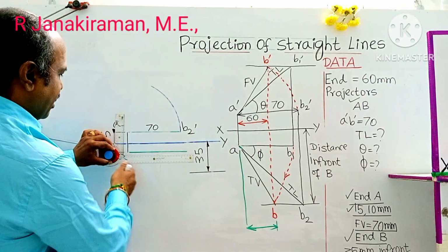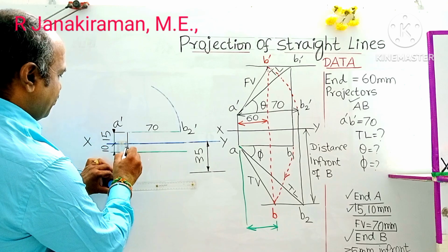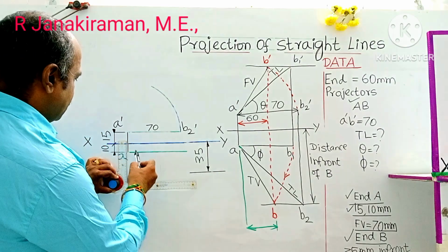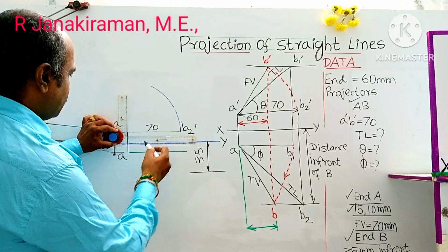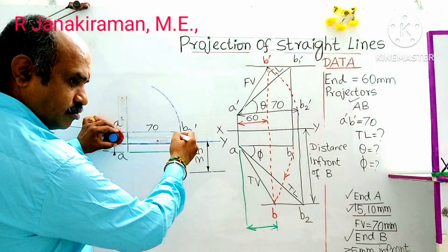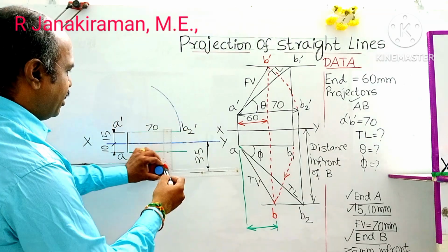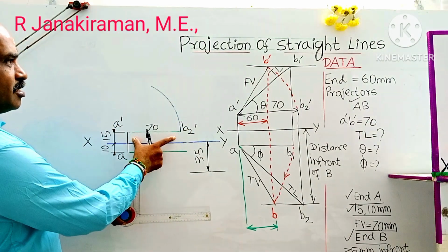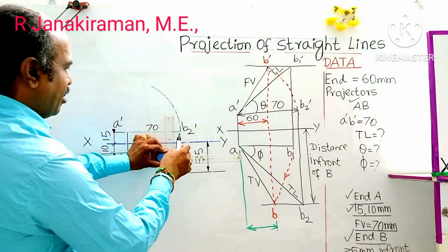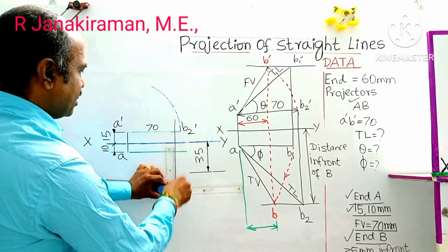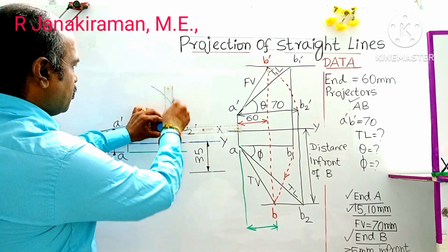So from this, using the drafter scale, this vertical line will be 0. Correspondingly, you mark this horizontal distance. There this distance is 60 mm. There you draw one vertical projector using the vertical scale of a drafter.